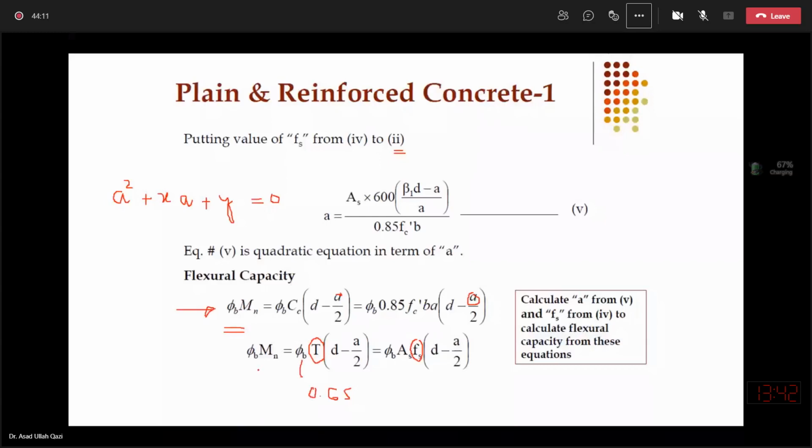So this is what will become important when you are analyzing an over reinforced cross section. So you get the idea from the rho value, that suppose your rho comes out to be greater than rho balanced in the given cross section. You are doing the initial classification screening and you got the idea that in your given cross section rho is greater than rho balanced. So there is a big hint for you that you are actually dealing with an over reinforced cross section.